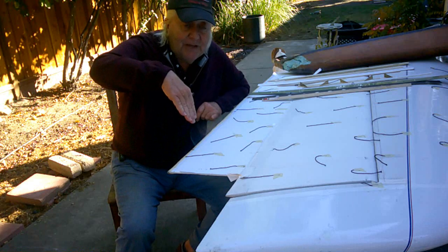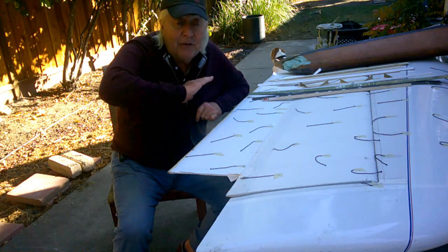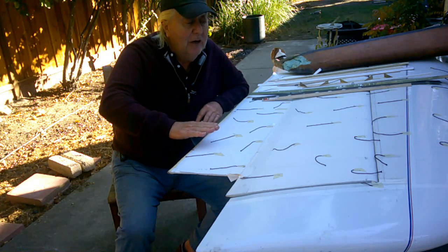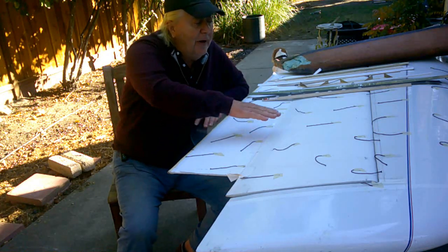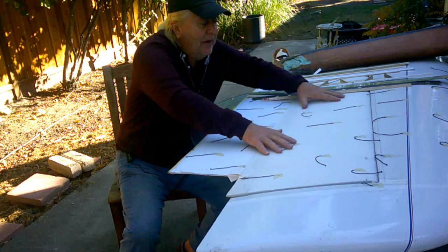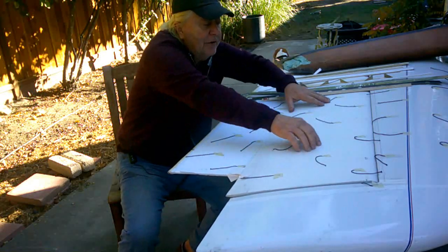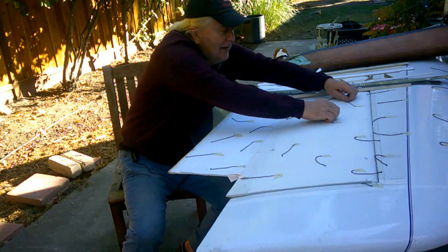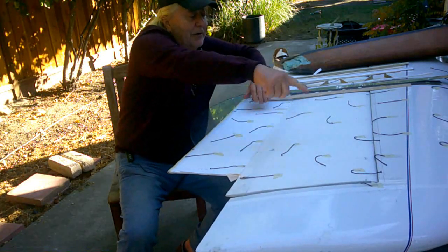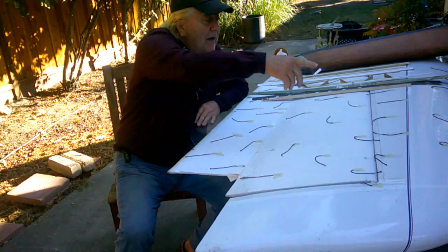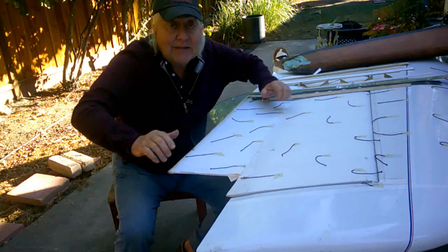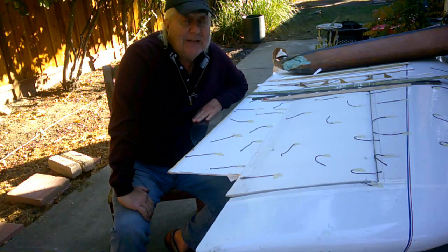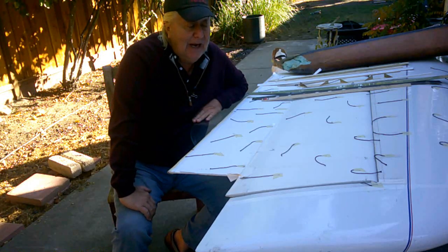The elevon's deflected down, we get separated flow, it goes out to the tip, but even when the elevon's up, there are situations where the flow begins to separate, and we see these tufts doing all kinds of weird things. You might see some circular flow like this, where these guys are pointed out and these guys are pointed in, so there's some kind of circulation going around here. Chaos, aerodynamic chaos. So that's indicative, and we'll go take a look at that.